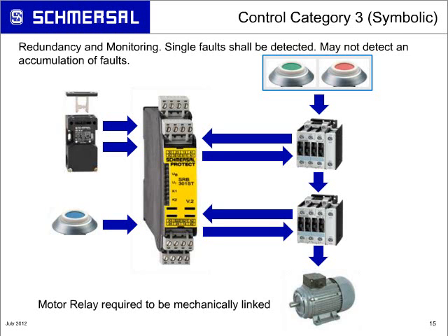you see a single safety interlock switch, but you have 2 arrows. You have 2 independent channels of signals coming from the safety relay back into the switch and back to the relay. If one channel fails, the other one still ensures a shutdown of your machine.